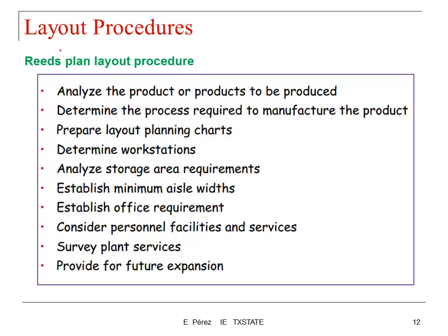Analyze the product or products to be produced, determine the process required to manufacture the product, prepare layout planning charts, determine the workstations, analyze the storage area, establish minimum aisle width or requirement, establish the office requirements, consider the personnel facilities and services, including restrooms and so on, survey plan services, and provide for future expansion.